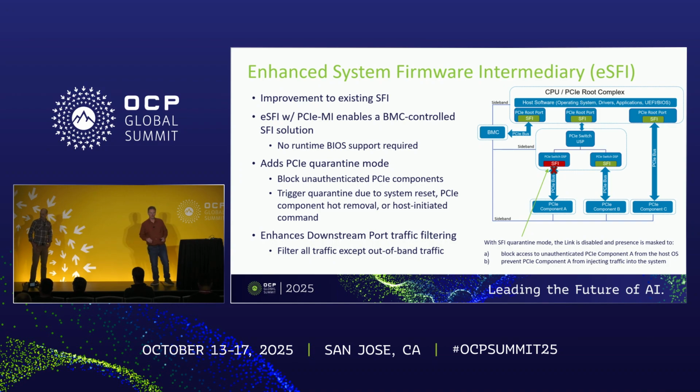Getting into what is in eSFI: eSFI takes the existing SFI and extends it. It really takes a lot of the stuff that was in SFI and makes it something that's enforceable. The big thing added is quarantine mode. Quarantine mode lets the system manager control when links come up, so you can power on devices with links down, and then manage when devices actually get pulled into the system.